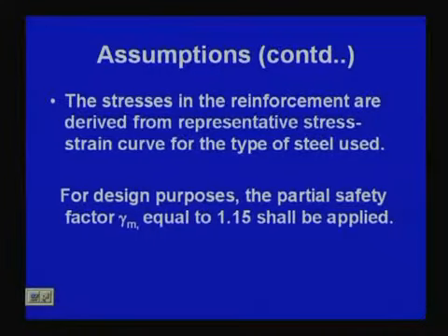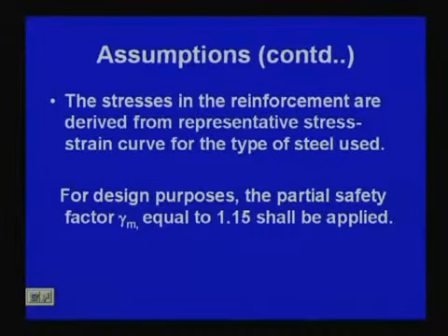For design purposes, the partial safety factor gamma m for steel we consider 1.15. So, if Fy is the yield stress, we have to consider Fy by 1.15, that is for design purposes.